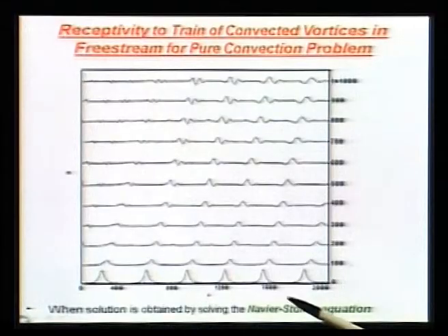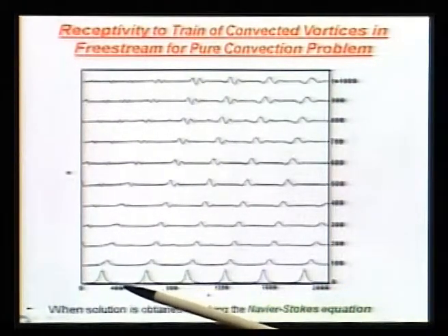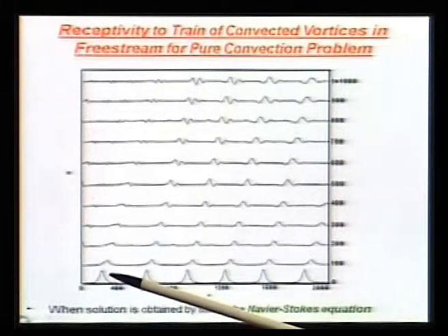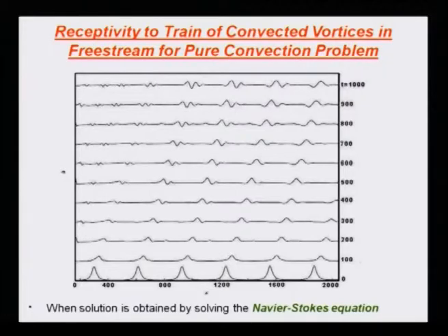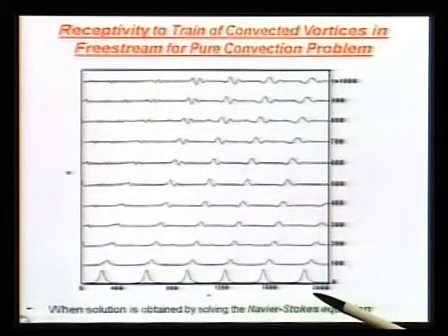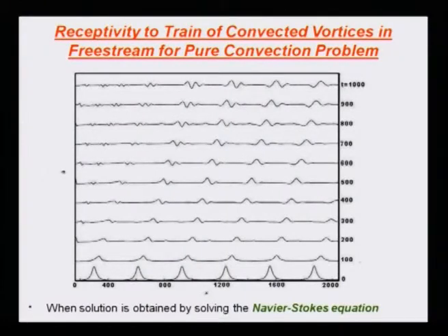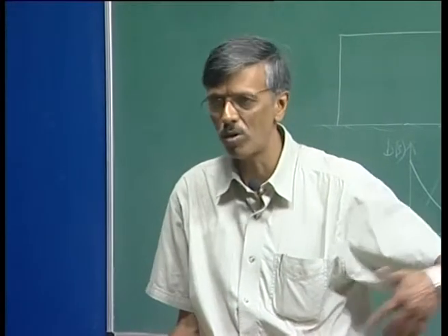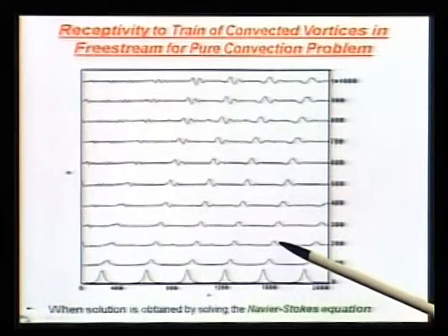And you see, in the free stream we had vortices at an interval of 100 pi. So, at t equal to 0, this is the solution. You see at the foot of each of the vortices in the free stream, we get some kind of a peak. And at t equal to 100, what happens? That same disturbance decays, because we have seen that the neutral curve c equal to 1 corresponds to a very decayed solution, and that is what you are seeing. This peak is coming down.